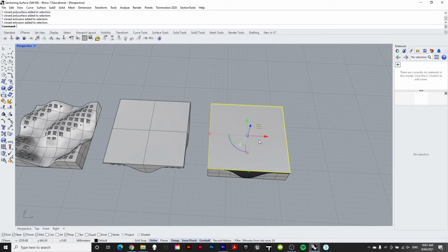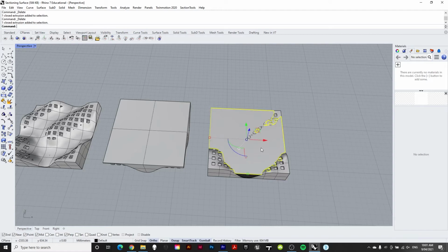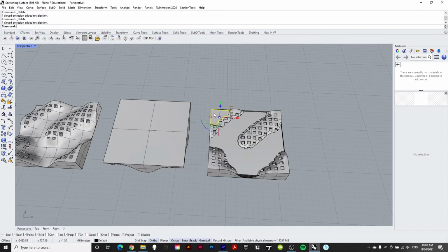If I delete each one of these layers, this would effectively be the toolpath of the CNC. It takes away 1 to maybe 3 millimeters at a time, depending on the size of the bit. Sometimes we can do more than that with thick bits, but we're going to lose a lot of the fine detail as well. So each one of these deletes that I make is another layer that the CNC would be going through. So you can see that this would be traveling all the way down, slowly carving away and revealing what is left behind inside there in terms of the geometry.